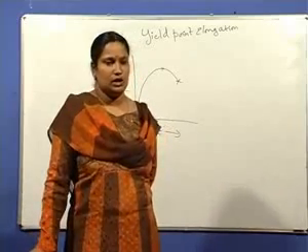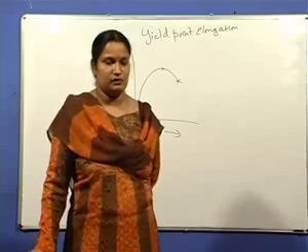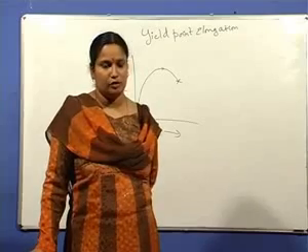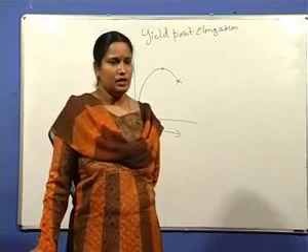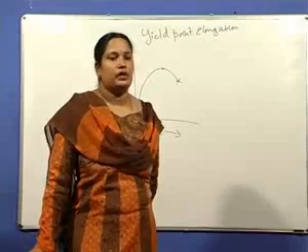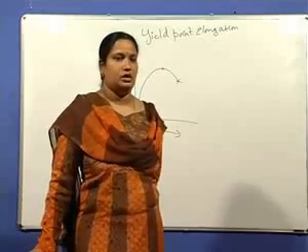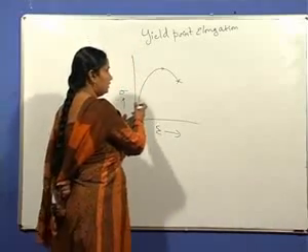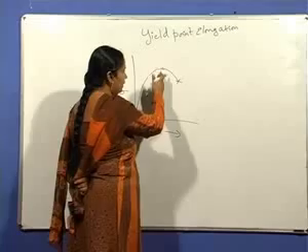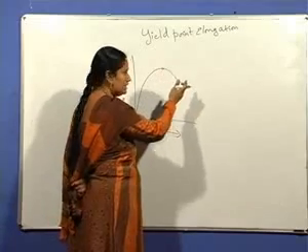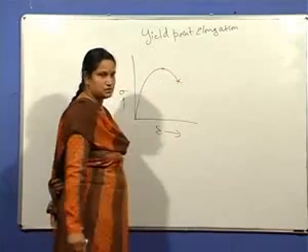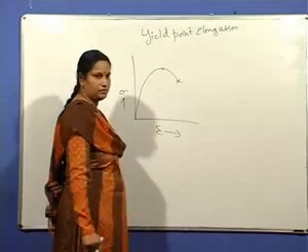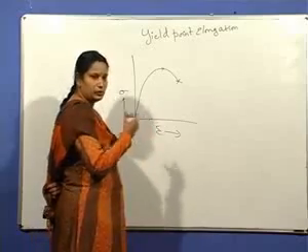Uniform elongation, total elongation, all this has been discussed very briefly. In detail, we will cover this topic under the heading of tension test. But for the discussion of yield point elongation, there are two types of curves. One is the normal stress strain curve, which undergoes strain hardening, and then beyond ultimate tensile strength, the curve drops, and finally the material undergoes failure. This is the normal one, which you have already known.